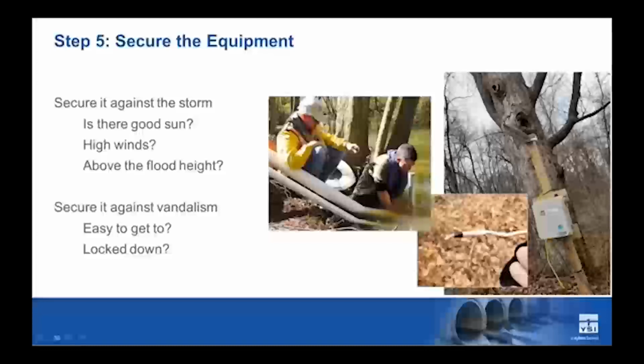This is a great site they have. It is a stormwater monitoring site, and someone stole their solar panels and cut some wires. I have a site here in Missouri where I am where somebody got a hold of the sonde, took off the sensors and threw them in a campfire. So these things happen. And securing your site against vandalism is definitely something you have to think about when you're placing anything in either a rural or an urban environment.